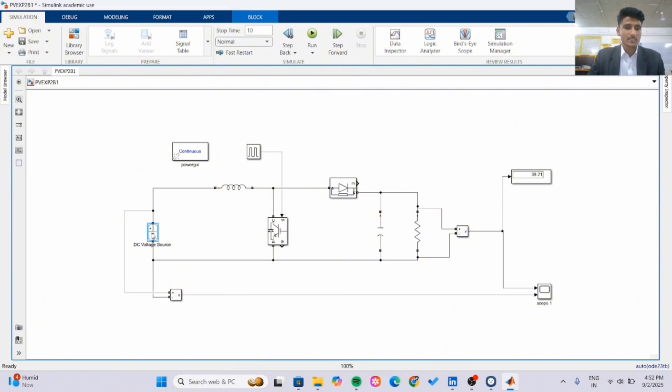So the DC input voltage plus the energy released by the inductor both add up and get boosted. The boost converter boosts, and it is also known as a step up for the DC voltage. It steps up the DC input voltage and gives a stepped up DC output voltage. This output is then given to the load, and here the voltage is measured and displayed.